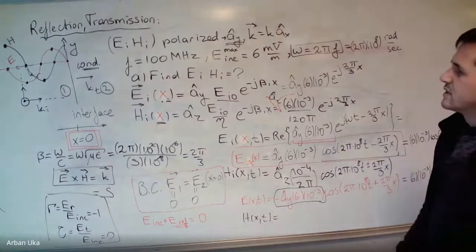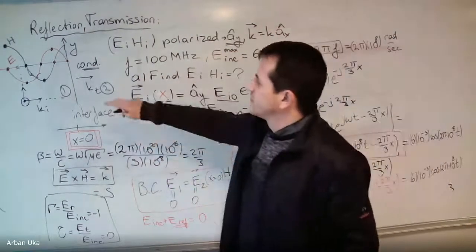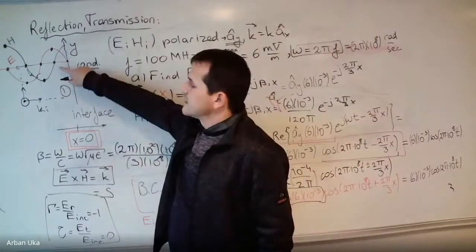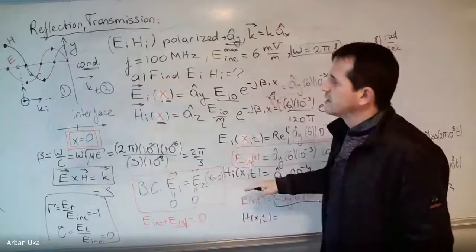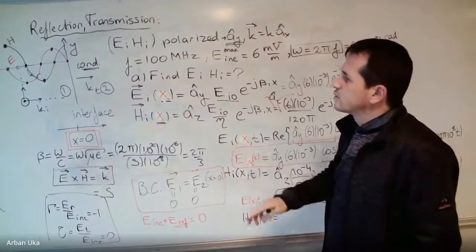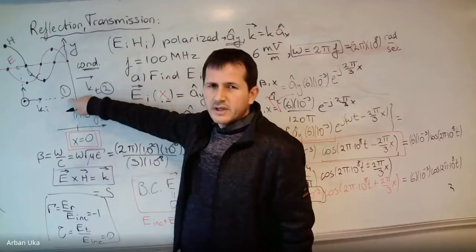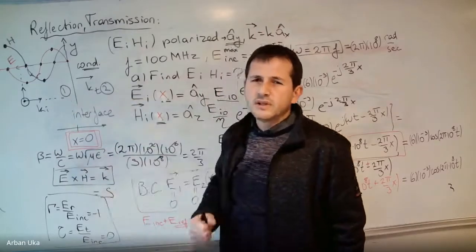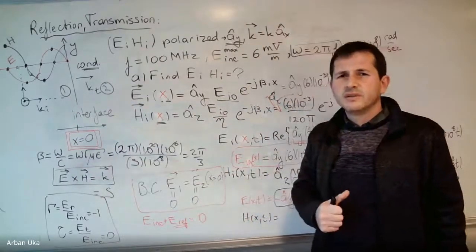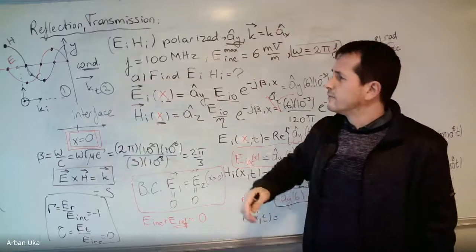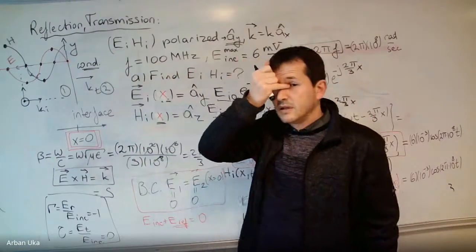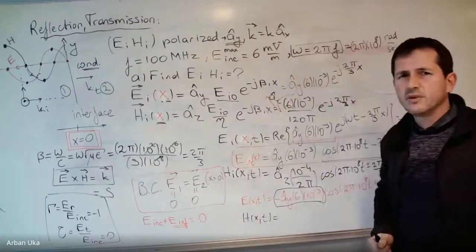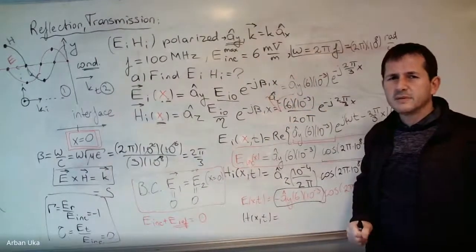But what we see here are not the incident and the reflected waves. This is the wave in medium 1, and the wave in medium 1 is equal to the incident wave plus the reflected wave. So the summation between these two has to be out of phase, but not the incident and the reflected one. Is it clear?